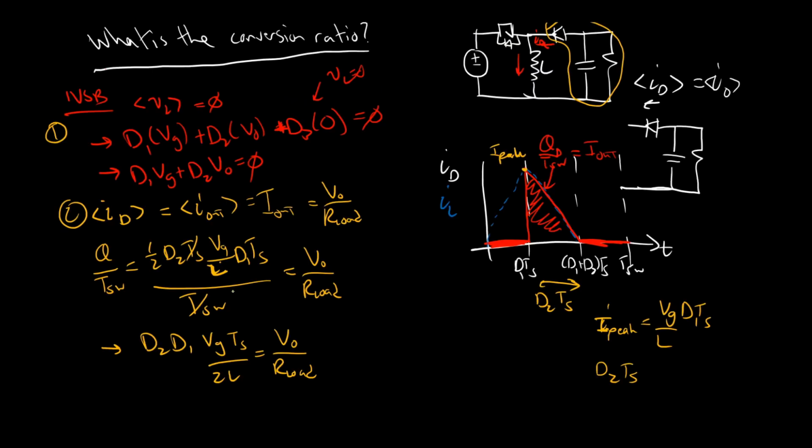Okay. So actually it looks like I've forgotten a minus sign. And that minus sign is exactly here. That's only because if I assume this is a positive V out, then I out should flow in this direction, which means that the average ID is equal to minus average I out.